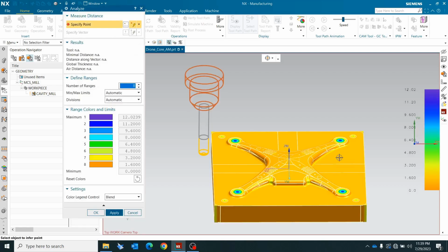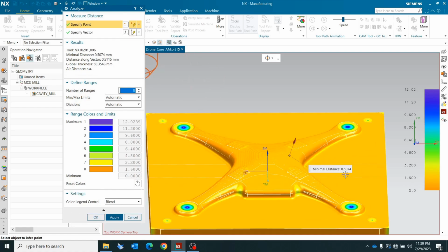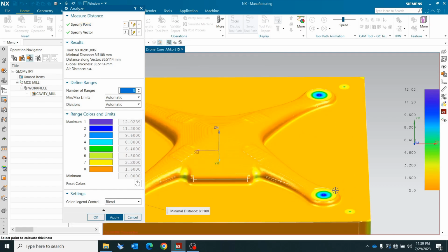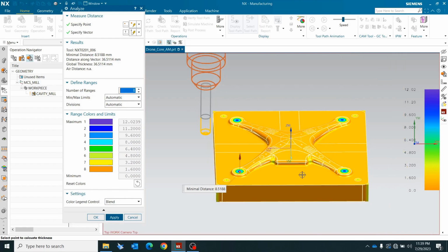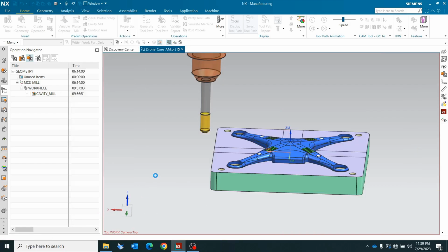For that, those small pyramid structures were created. Now you may not see 0.5 mm, 0.5 mm, 0.5. Yes, it's correct. Here, if you see, there is an 8 mm; my cutter has not gone inside that. It's okay. Like this, you have to create a cavity mill operation.